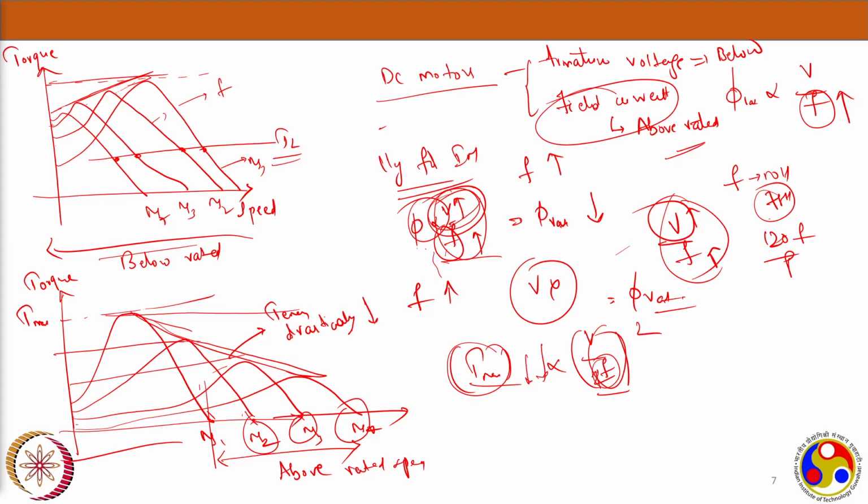And yeah, another interesting point here is we discussed many starting methods, right? Reactor starting, auto transformer starting, star-delta starting. I discussed this point before. But here, if I have this kind of inverter, which is variable voltage and variable frequency, I can also think of starting my machine using this entire setup.